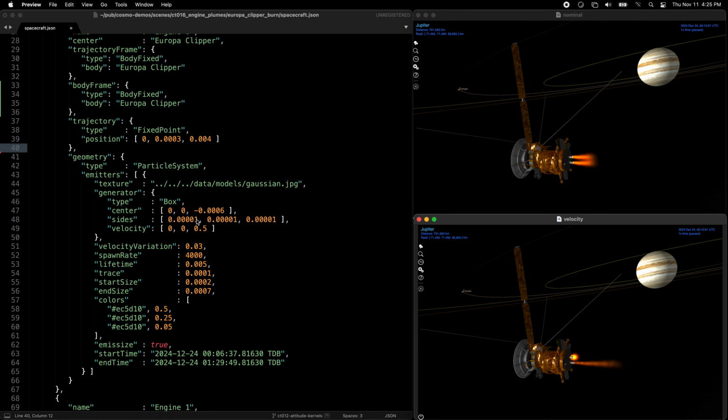The size variable defines how far out the particles can be emitted in each direction, so we found that if we make the y and z too big, the particles come out with larger than desired non-axial velocity. The velocity variable is the nominal velocity vector of the particles, and this is nominal because the next setting controls how much the particles deviate from this vector.